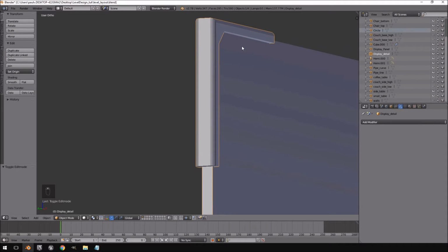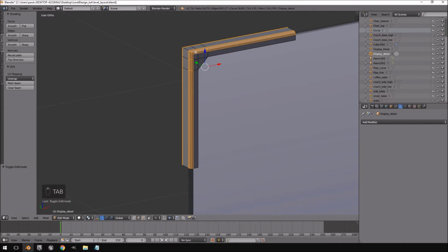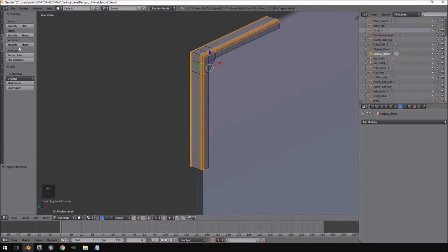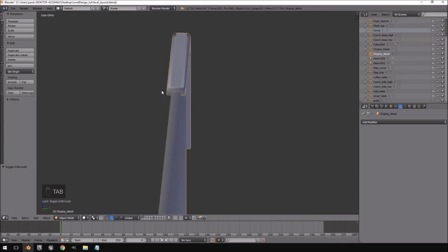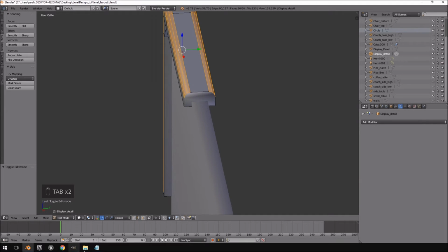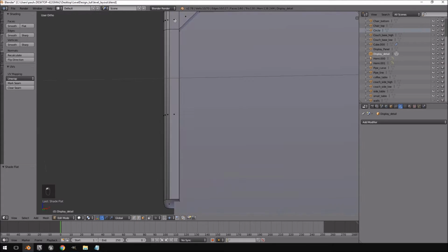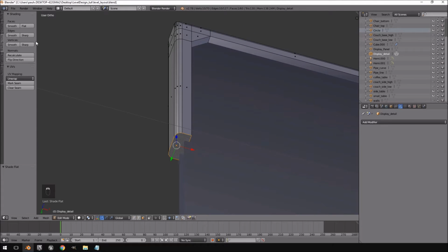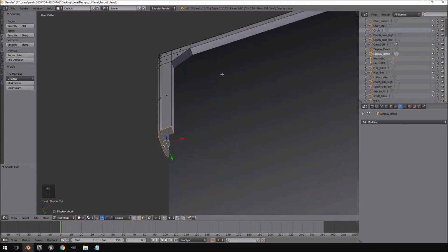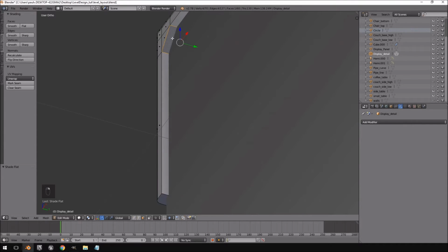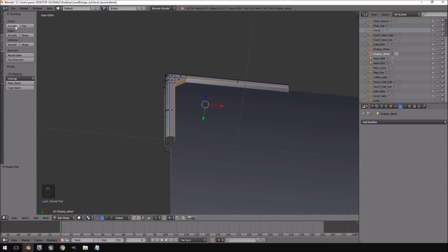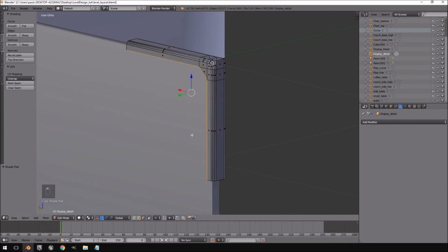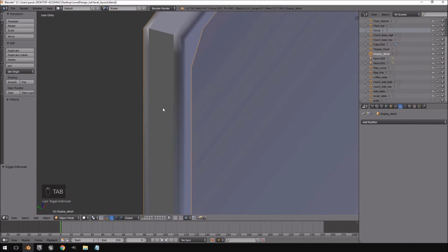Alright, so this entire area here, I'm going to select smooth shading on. We're going to smooth those faces out. And actually, that one, flat shading, and this one, flat shading. Okay, so we can also then just select the other faces as well, and we're going to make those flat shaded as well. So it all really depends on how you want this to look.